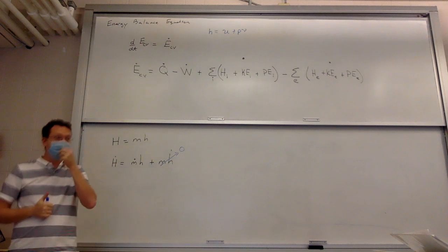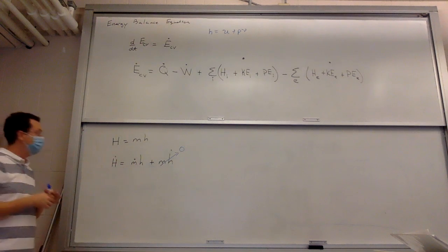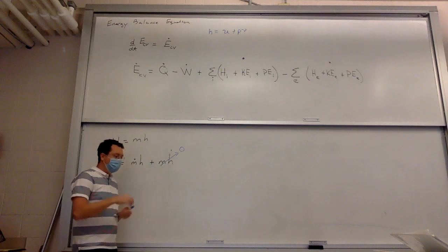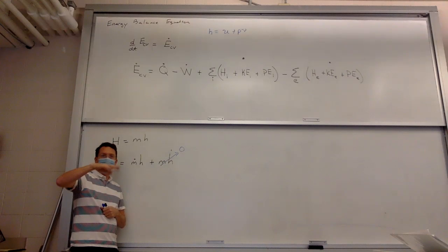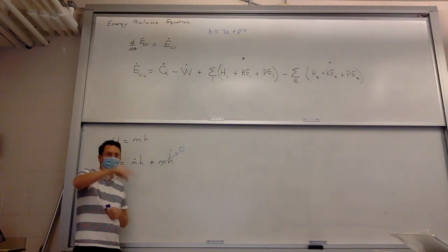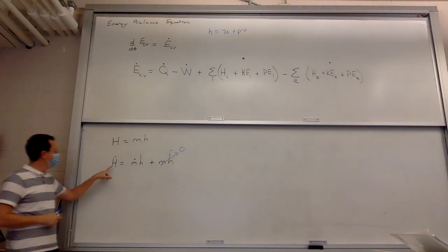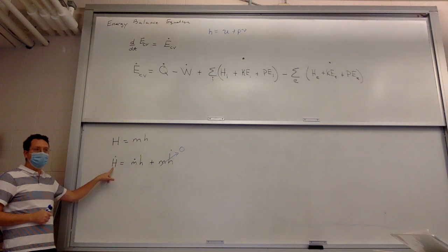Now, to justify that, you have to put numbers, but it's just true that a droplet here pretty much looks like the droplets next to it. They all look about the same. So they're individually not really changing. So the overall rate of change of enthalpy just comes from adding more or less drops of water, not really the time change inside each individual drop.